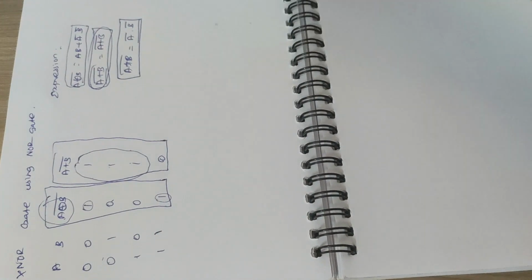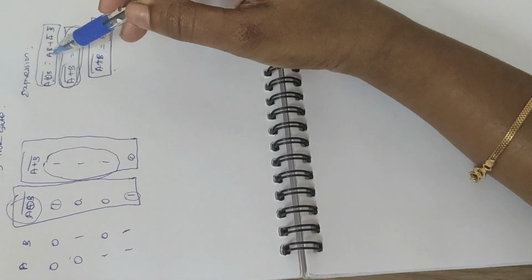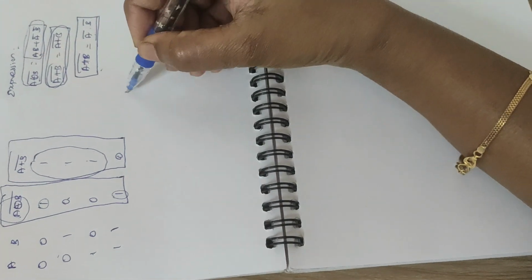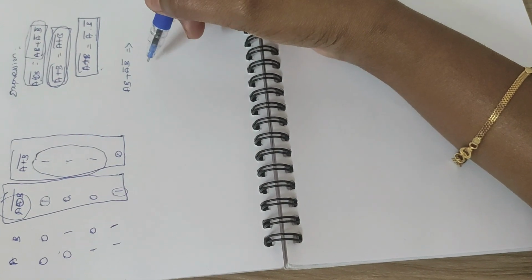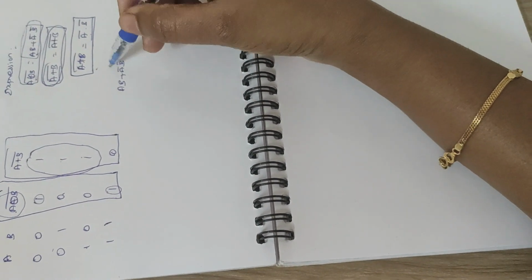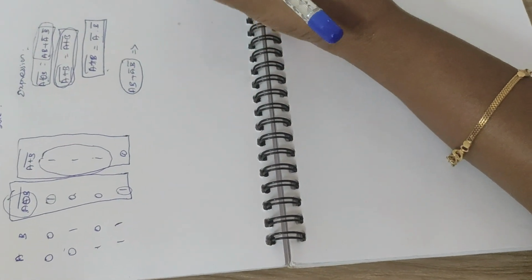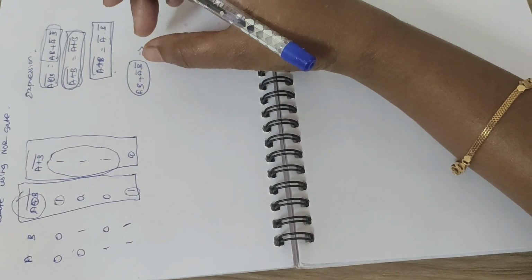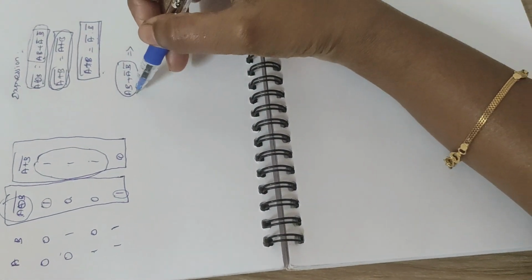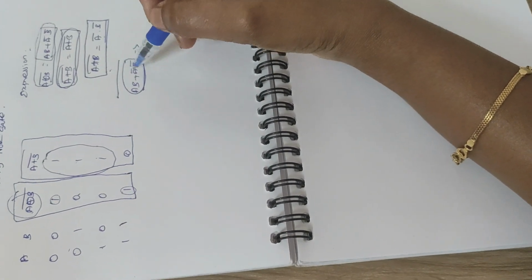So we'll start from the final output NOR gate. Here A plus B the whole bar equals A bar B bar. But what we have to implement is AB plus A bar B bar. If you see, it is not in the form of a NOR gate; it is in the format of an OR gate. Even if it is a product form, we can do something like a double bar, and it will become an OR format that we can use directly. But since it is already an OR form, if I put another bar here, it again won't become a NOR.